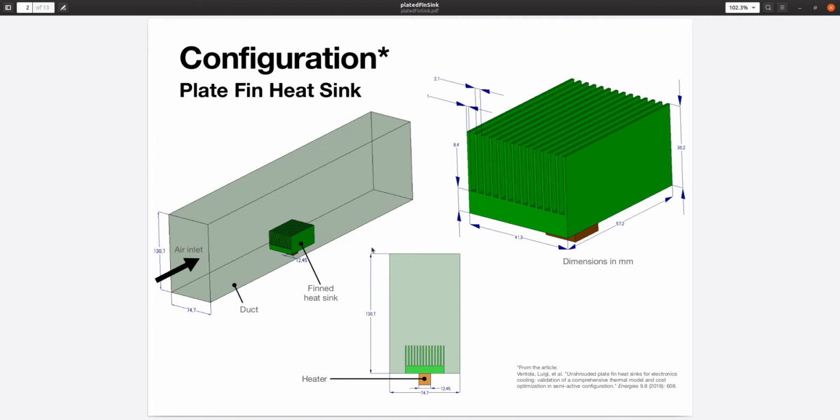The objective of this tutorial is to explain the whole workflow, starting from creating the regions for each solid region and for fluid, making boundaries, creating mesh in Salome, moving this mesh to OpenFOAM, setting up a case in OpenFOAM, and doing some post-processing.